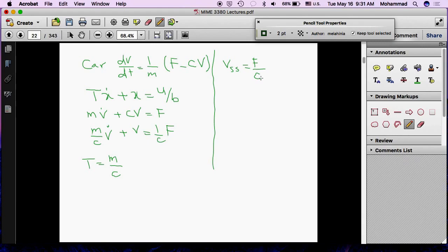That's exactly the reason. The reason drag plays this role that is counterintuitive is the drag is what causes us to reach steady state in the first place. So the more drag you have, the faster that transient would be over. Can you relate to that? The more drag you have, the sooner you get to that balance. That's the meaning of that. It has nothing to do with how fast the car will travel in this analysis. It simply says how soon that transient period would be over. That's it.